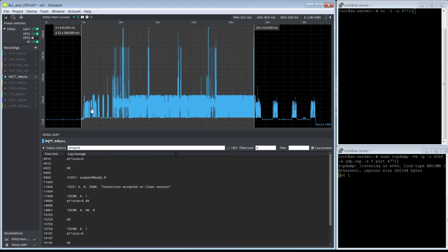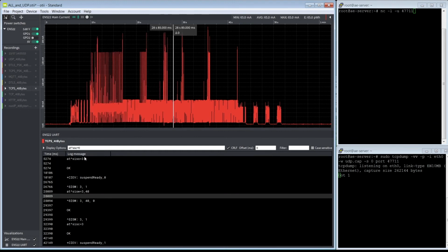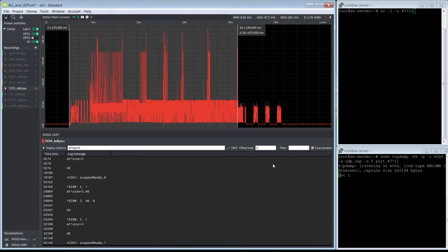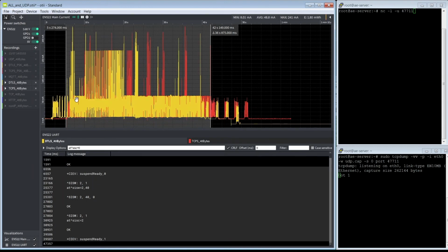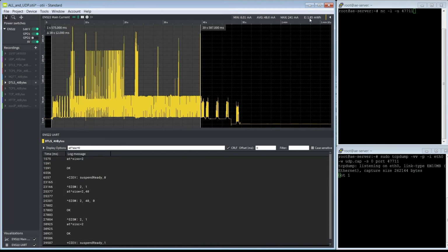And if I now go into security parts, for example, I use TLS, so a TCP connection which is secure. We see a much higher power consumption. Of course, there's a need to do the crypto part, and there's a longer handshake as well. It is possible to make UDP secure as well. This is called DTLS, and DTLS needs a high amount of power. It's about 1.8 milliwatt per hour.